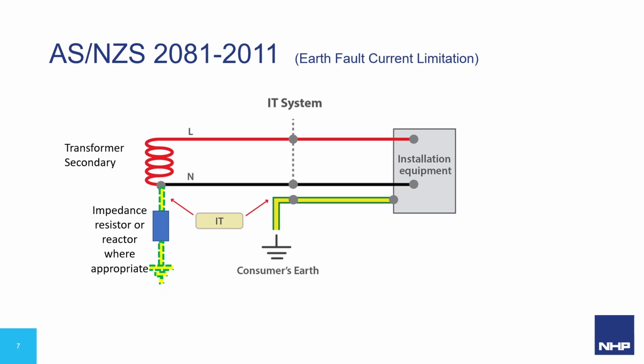The major difference with the mining and quarrying reticulation system is the use of the IT network and earthing systems. In many mining applications, standalone generator systems are used for power supply to the site. The IT system is best for maintaining safety in areas where there is abundant rock and broken ground.